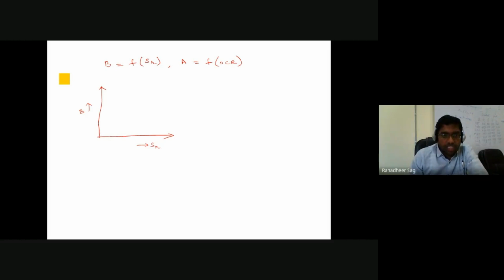In case the degree of saturation value is 0, the corresponding B parameter is also nothing but 0. Why is it 0? Because if soil does not have any degree of saturation, it means it is a dry soil. In dry soil, you don't talk anything about excess pore water pressures building up in your soil sample. That's the reason why your Skempton's pore water pressure parameter B is equal to 0.